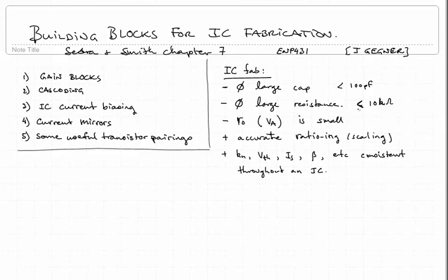The transistor output resistance, which, if you recall, appears across the controlled current source. If it's a MOSFET, then we have a drain and a source, and there's an RO across there. And that RO is small for modern IC fabrication.